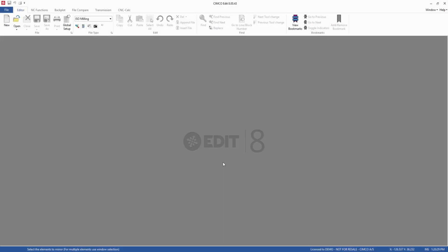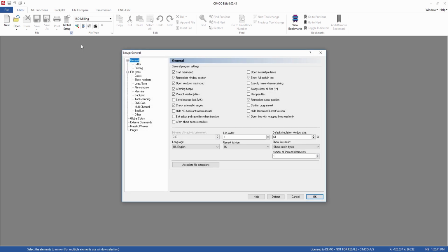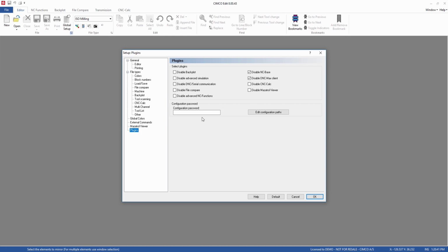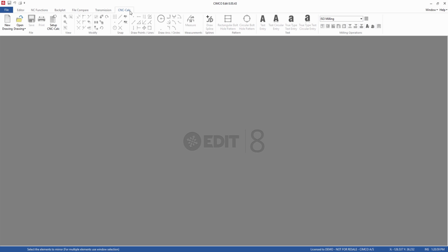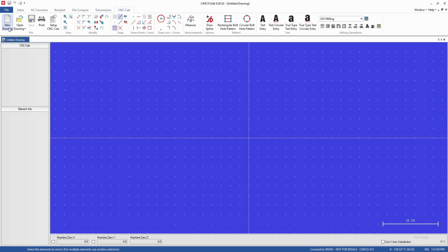Hi, in this video we're going to draw the milling geometry in tutorial 1 of the CNC Calc manual, which is available on the website. First thing we're going to do is go into the setup and make sure that CNC Calc is enabled. So we go into plugins and make sure that there's no tick in this disable CNC Calc checkbox. The CNC Calc tab is on the editor toolbar and we start a new drawing.